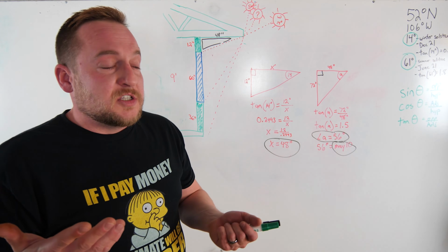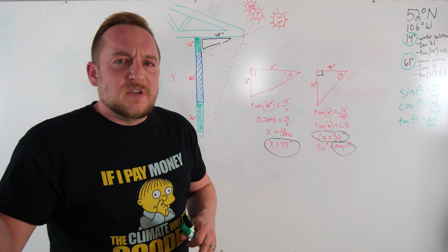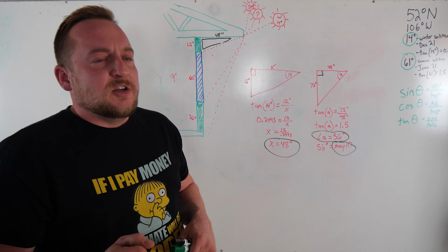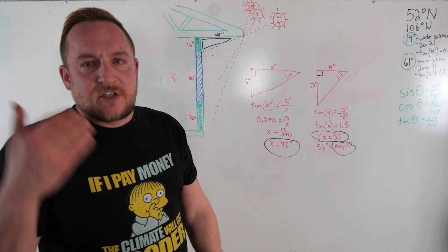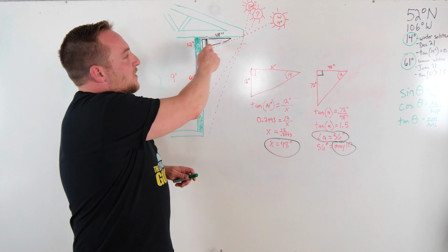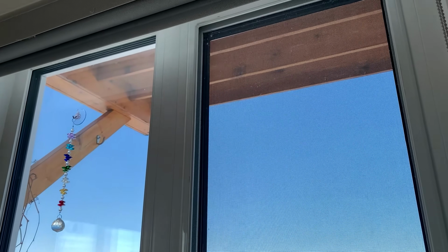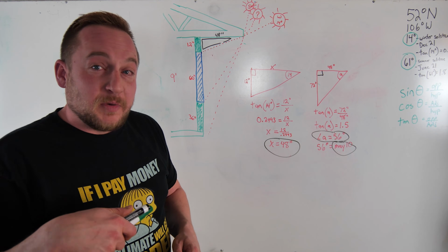But in the off chance you have a retrofit situation, maybe your house has a few south windows, and you notice in the summertime, holy cow, it's hot, and your air conditioning bill is high. Well, you can build a little pergola sun protector, the right height above the window and the right length out on a south window, to protect against the summer sun heating up your house.